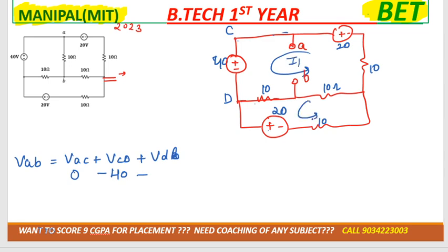This one is I1, this one is I2. So positive, negative. So minus, second sign, 10, and as you can see, this 10 ohm is in the middle wall, and in the middle wall there is a flow of double current. From this side I1 is flowing and from this side I2 is flowing. So it would be I1 minus I2. This is the value for VAB.